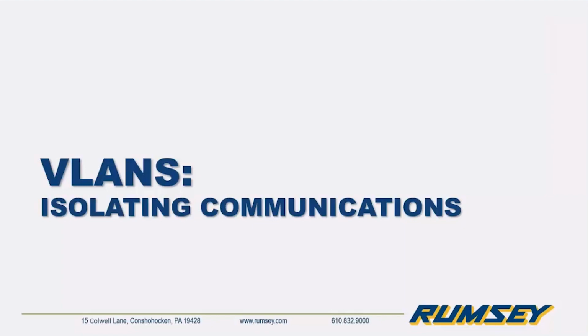So, some context behind that. In a typical IT system, multicast traffic is not really relevant. It's rare at most, at best. We see way more multicast traffic in an industrial environment, just given the nature of the endpoints. Your typical PC isn't doing anywhere near as much multicast traffic as automation endpoints. And to your point, we have definitely run into a ton of situations where it's like, oh, well, we have IGMP snooping enabled, but there's no querier. So you don't really have any positive effect without both of those active.